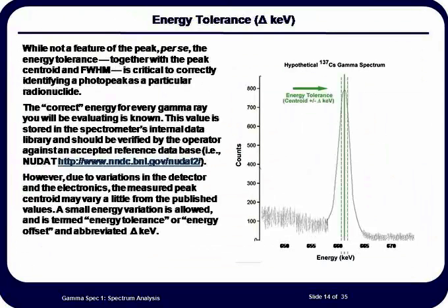Keep in mind that the peak centroid will shift due to minor fluctuations in temperature, humidity, line voltage, and background radiation from other radionuclides. Thus, when the user selects a delta keV preset value, it should be based somewhat on the experience with the instrument at hand and the type of samples being measured.